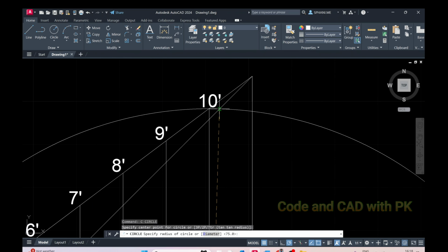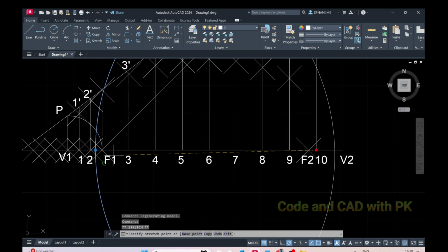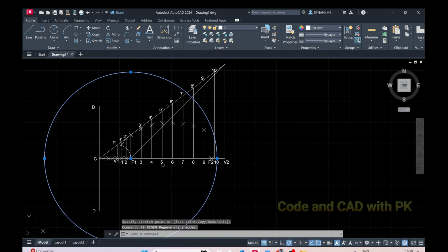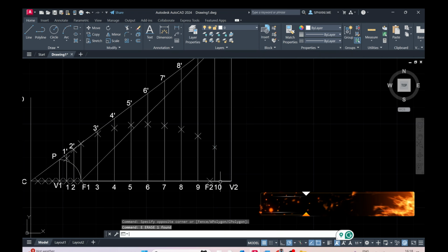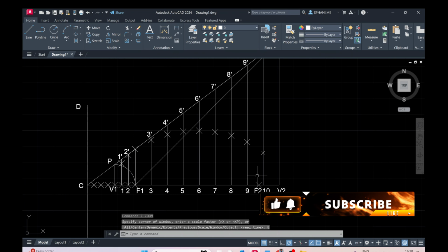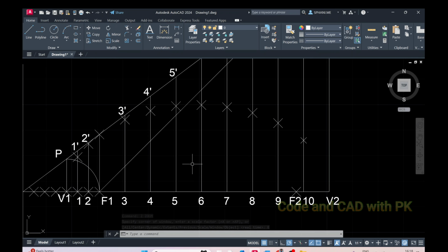And again next, circle, C, 10 and 10 dash radius, move the circle from this point to this point. Enter, okay, locate the point P10, enter. Here this is my point. I am going to delete this circle. If you observe, I have already located all the focus points. Now what I am going to